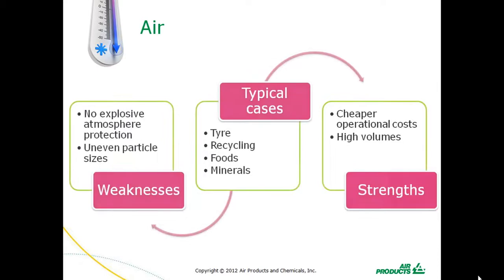This is the lowest cost method and is often used in coarse grinding applications. A downside of using air to cool the grinding process is that it has a limited cooling capacity and can therefore limit the particle size the grinding system can produce.